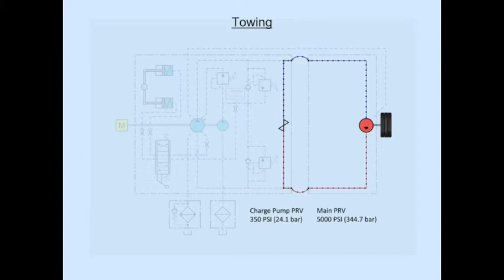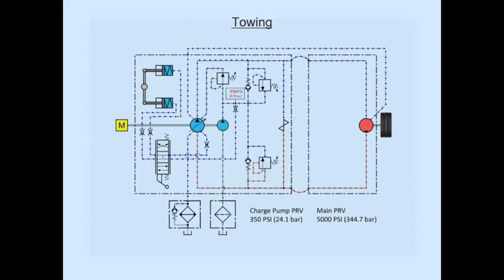It's going to trash it. So you don't want to do that. But the next thing you want to be careful of is the manufacturer, if it's got a towing bypass valve, will give you 2 precautionary statements. 1, don't tow at more than 3 to 5 miles an hour. Well, that's probably because it's a piece of construction equipment which looks really bad going down a freeway at 100 miles an hour while it's being towed. So 3 to 5 miles an hour is a safety thing. And then the other thing they might add is don't go more than 500 feet. The reason why they're telling you that is because the charge pump is not running. And you've got high pressure, you're creating resistance across this valve, which means you're leaking internally, but you're not putting the oil back. So it's eventually going to run out of oil. And that's bad news.